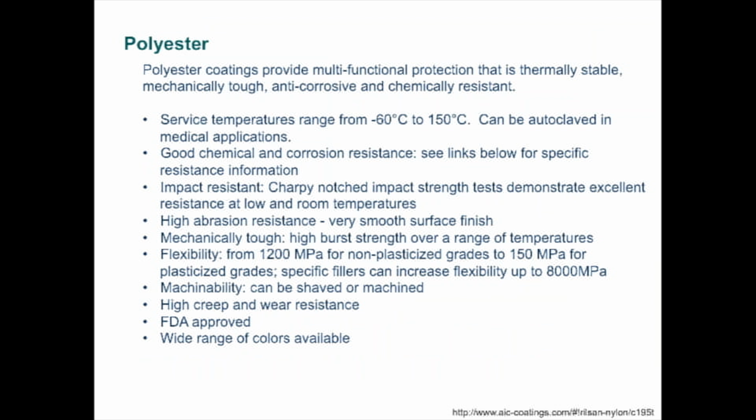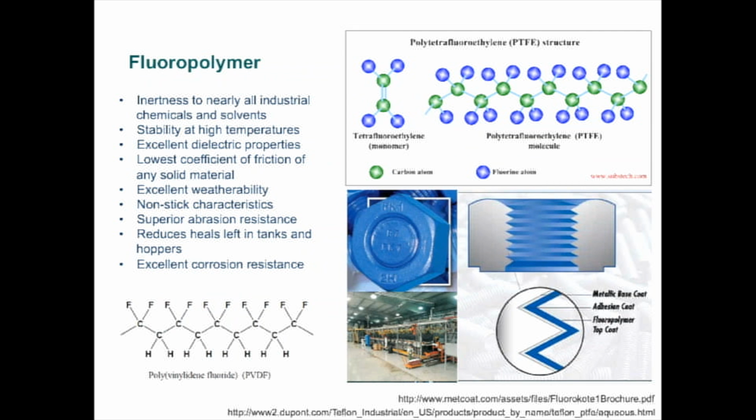Polyesters are quite useful, a very good combination of properties that resist corrosion as well as chemical resistance. So overall, it's competitive to polyurethane in some formulations. Fluoropolymer is a more expensive material. Obviously, the famous polymer there is based on Teflon, okay?